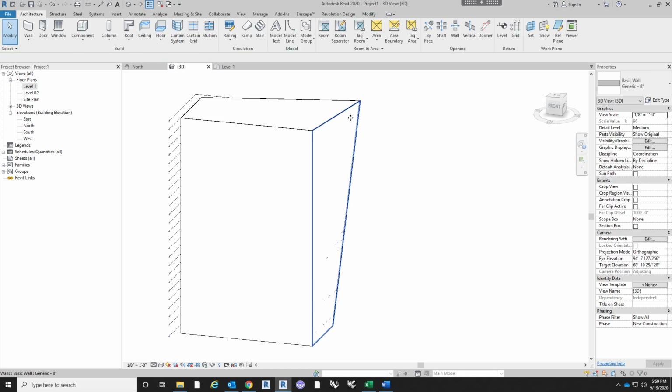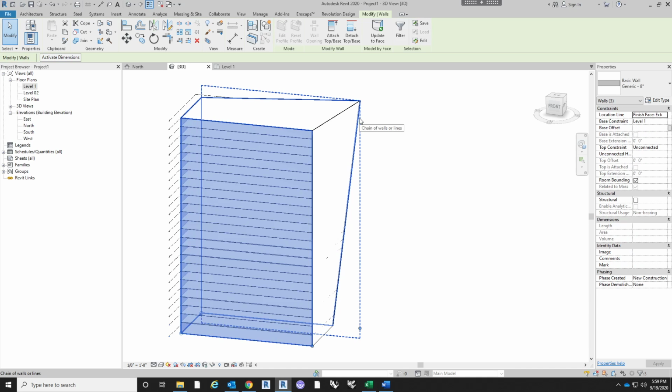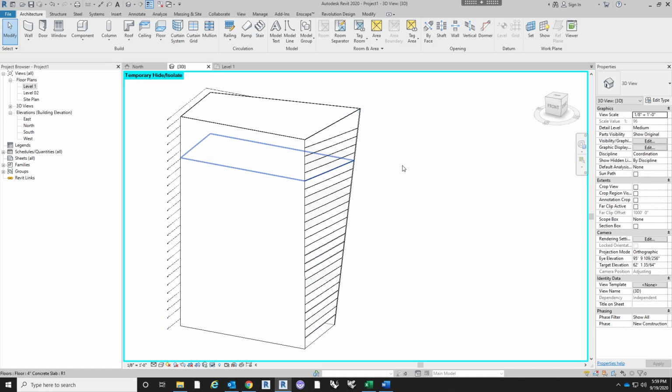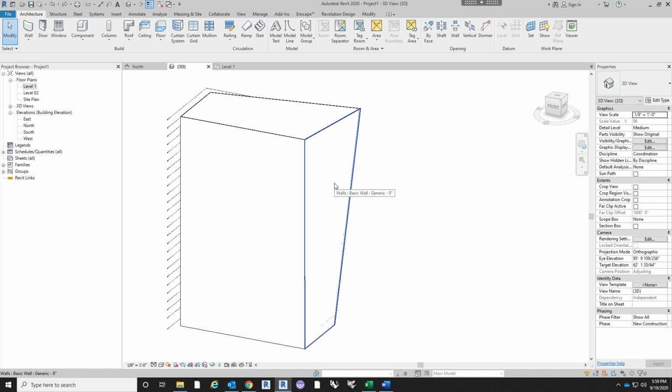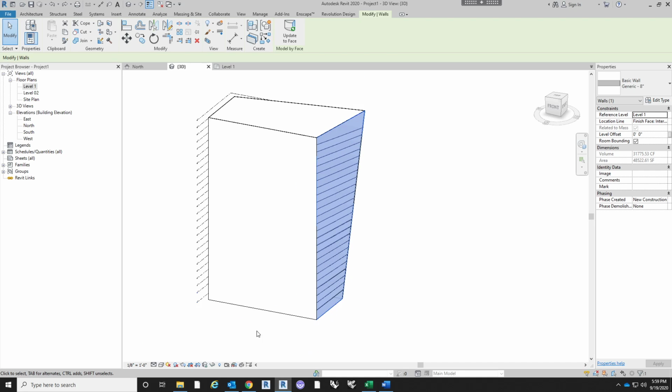Same thing as before with editing the mass. And I'm just going to hide this real quick. I guess I'll go over that right now. If you want to just temporarily hide something, what you can do is click whatever element you want to hide, go down here to this sunglasses icon, click that and then do hide element.